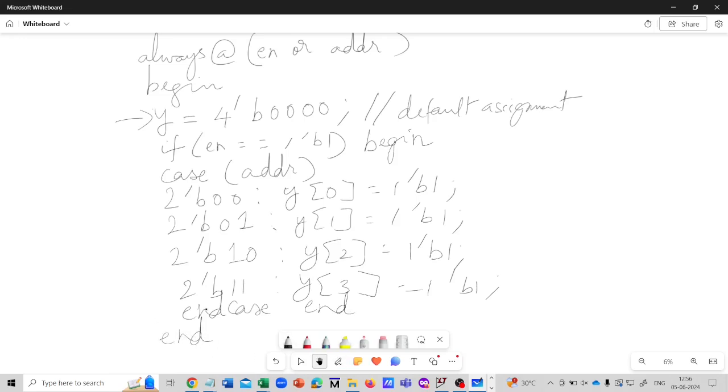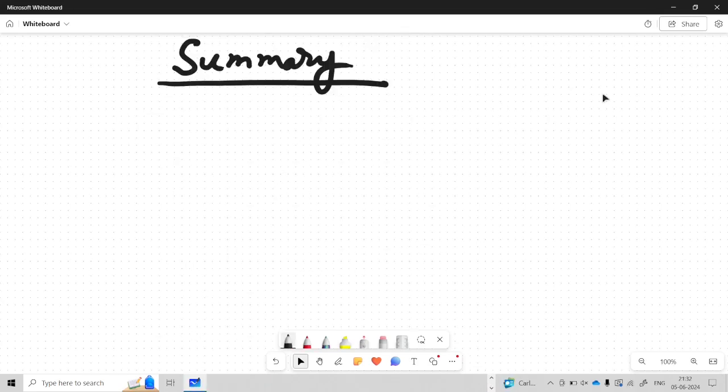That's it. So you can see how elegantly we have solved this problem. Just by a single default assignment, all the unspecified branches of the if or case statement are taken care of, and we are able to avoid unintentional latch inference. So now let us wrap up the first part of the video on combinational subsystems. Let us try to summarize the important points that we have learned during the course of this lecture.